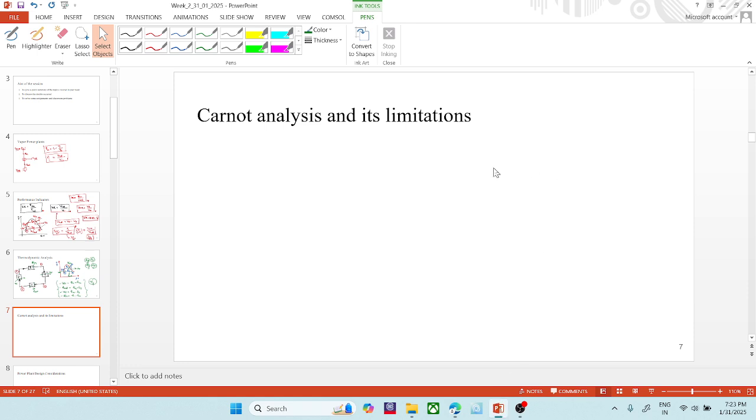Yeah. So here we have seen that we cannot adopt the Carnot cycle in the vapor power plants. The reasons are very simple. It is very difficult to handle the vapor and liquid mixtures. It is very difficult to compress it, and also in that case the pump work is very high. This is the reason we have to modify the Carnot cycle and go for the Rankine cycle.